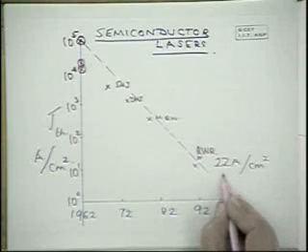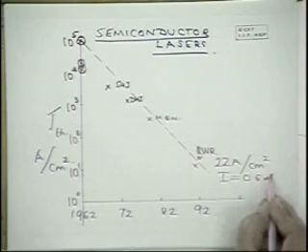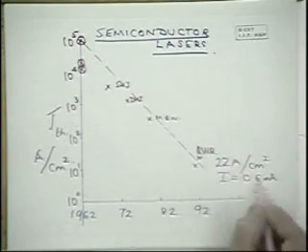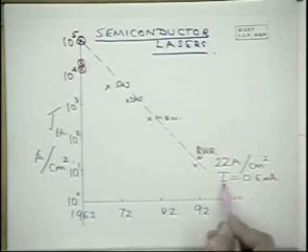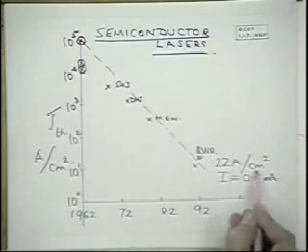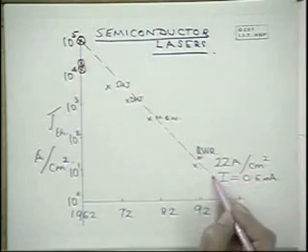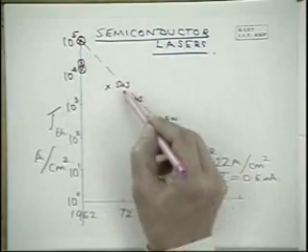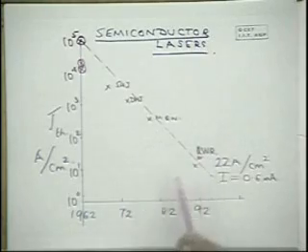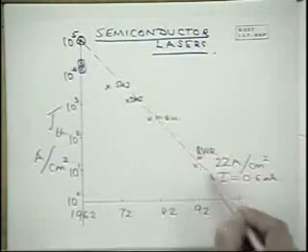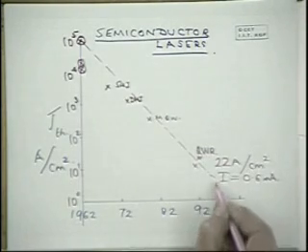There has not been a dramatic improvement, but this is about 0.6 milliamps. So a laser such as this can be run off just pencil batteries. The current consumption is so low, the power dissipation is so low, that it becomes a very handy portable device. So you see that through the use of firstly heterojunction technology, then quantum wells, quantum wires, using microcavities, we've had a dramatic improvement in the performance of semiconductor lasers.